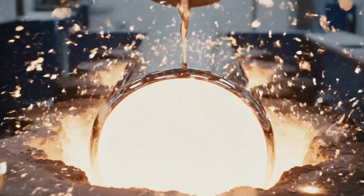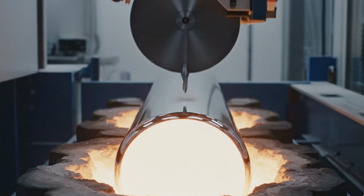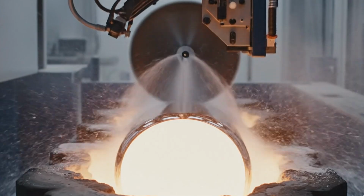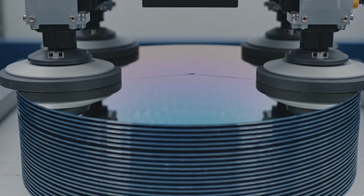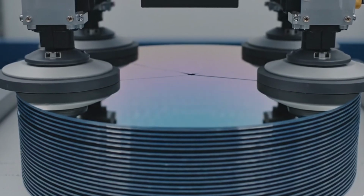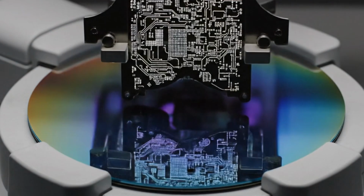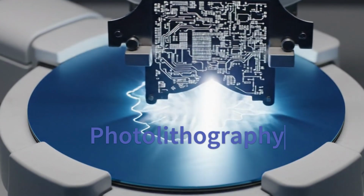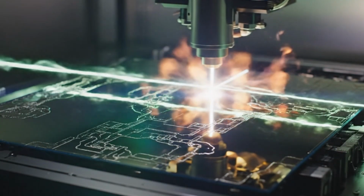Now let's understand how a modern chip is actually fabricated. The process begins with silicon, refined from sand into ultra-pure material and grown into single crystal ingots. These ingots are sliced into thin wafers which serve as the foundation for all subsequent steps. A thin oxide layer is grown to provide insulation and surface protection. Photolithography is then used to transfer intricate circuit patterns onto the wafer using light-sensitive photoresist and masks.